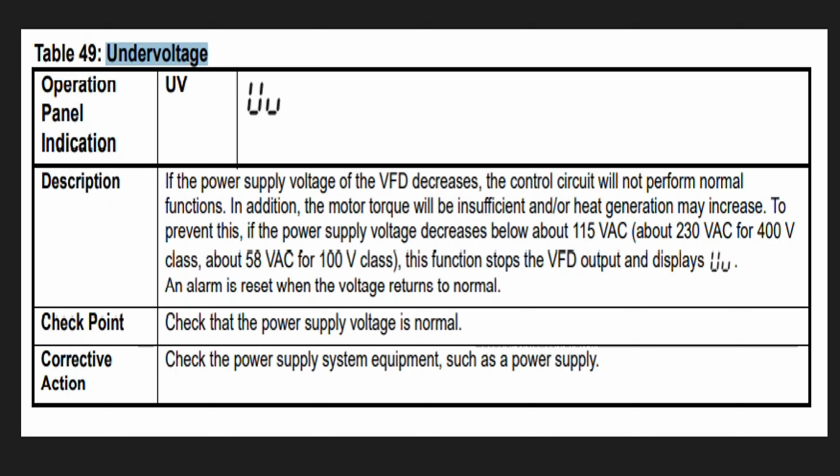So what happens is the VFD's rectifier section converts AC to DC, and then DC to AC. When there is no proper DC power supply after the rectifier section, this alarm occurs. So you need to check that all three phases are properly connected and not loose. That could be the reason.